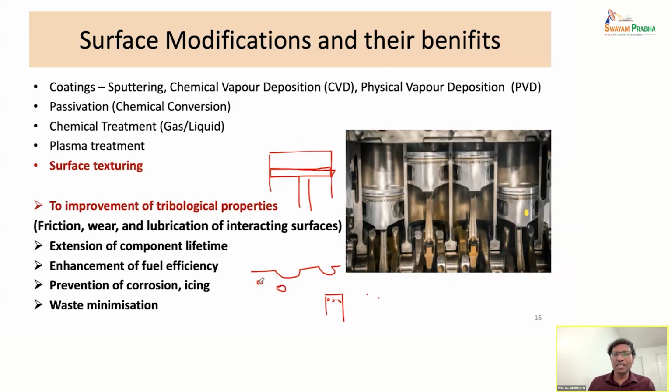And if the diameter of this hole is smaller, you get the smaller particle. So in that case, the oxygen surrounding the combustion will be more. But if these holes are larger and the fuel particle is bigger, it won't burn fully, and maybe at the core it will remain as fuel, and probably it will be scavenged and thrown out. So it is not efficient.